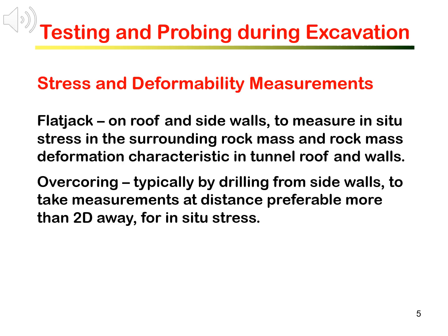For deep underground excavation, measuring initial stress and deformability can be expensive during surface site investigation. Those measurements can be taken during excavation, with tests done from excavated tunnels. Typical tests are flat-jack tests done on roof and side walls to measure in situ stress in the surrounding rock mass and the rock mass deformation characteristics in tunnel roof and walls.